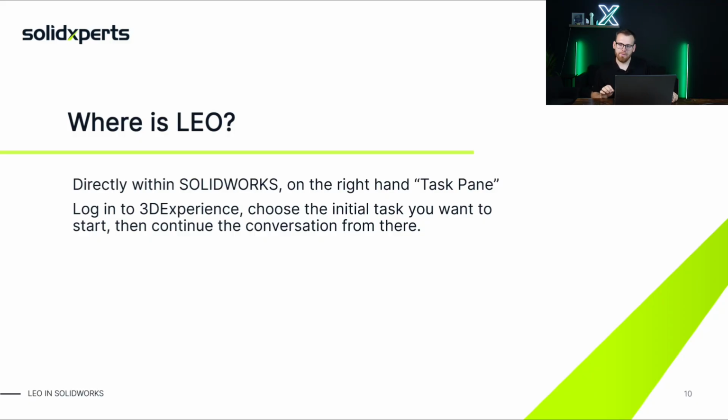And in order to see that, you want to make sure that you have the 3D Experience add-on downloaded, installed, and turned on. So you download that from 3D Experience Online. And then in the add-ons area, we check the box to make sure that the 3D Experience Connector tool is turned on. When it is, the AI Labs tab will show up, and it'll have all of the tools that we'll talk about today, as well as more, including another AI assistant called Aura.